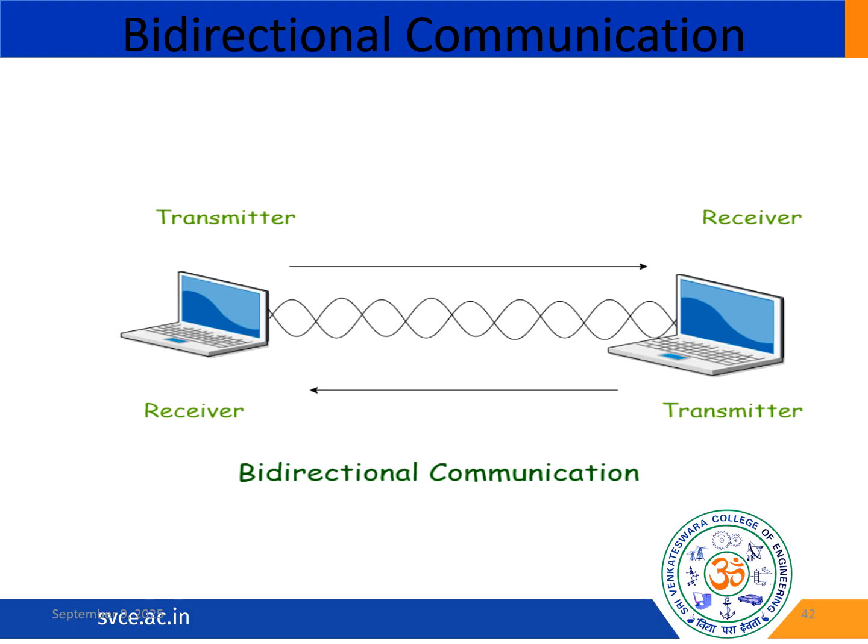As soon as a device receives some data, it can immediately respond to that data. Enhanced reliability is also possible, as it supports acknowledgements, error correction, and synchronization. Examples include TCP/IP sockets, web sockets, and industrial protocols; systems like OPC UA and MQTT support bidirectional messaging for control and monitoring purposes.